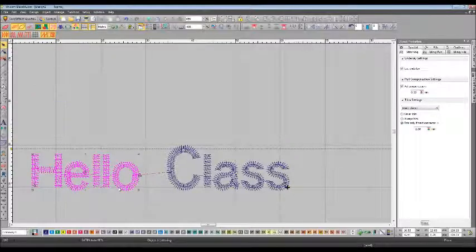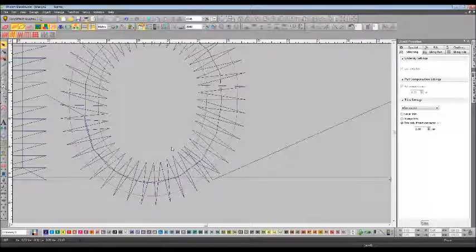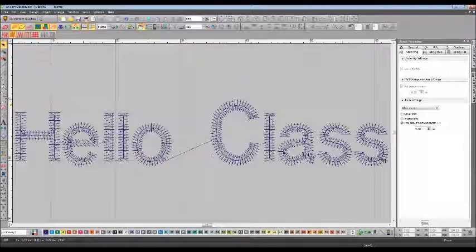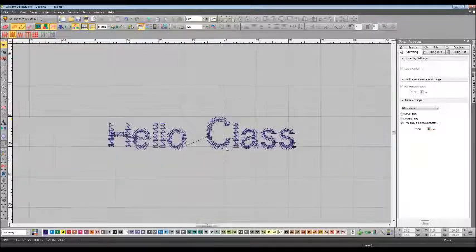So we can make this after object never trim. Get rid of that trim. And let's see if my theory is right. Did it tie off? Oh, it did tie off. Okay, because the connector is longer than a certain length, so it will tie off there. Well, I just made myself a liar. So there you go. You can hand trim that. See, you learn something new. Even after you've been using the software for so long, you learn something new that it does to surprise you.